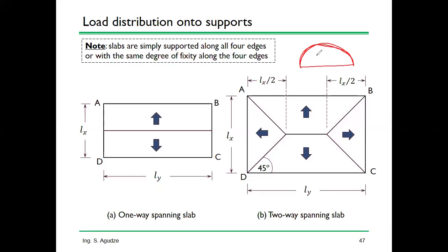So that one is a kind of complex system. And there's a table or a yield line procedure for some of these complex edges, complex slabs. But please, let's understand from the basic rectangular slabs so that we don't confuse ourselves. If you have a square slab, then at the end of the day, the whole thing will become like you cross it like this. So on all four sides, everywhere is a triangular load, based on this principle I've shown you.